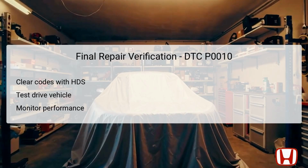After troubleshooting and making necessary repairs, the final repair verification is essential to confirm that the DTC P0010 issue has been resolved. Begin by using the Honda Diagnostic System to clear any stored trouble codes, meaning that the PCM will reset its stored memory regarding the VTC system.